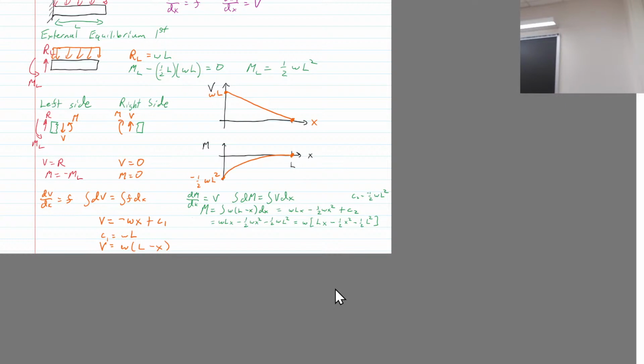But where is this located? It's located on the neutral axis. We just wrote that it's My over I, right? And if y is equal to 0, then there's no contribution to that stress. What do you mean A is on the neutral axis? So we should go back to section 16. Go down.